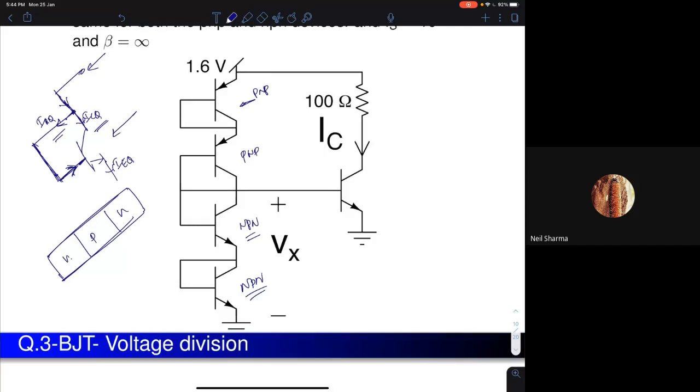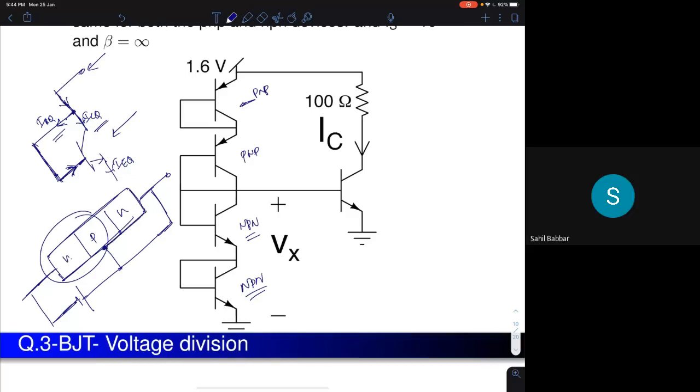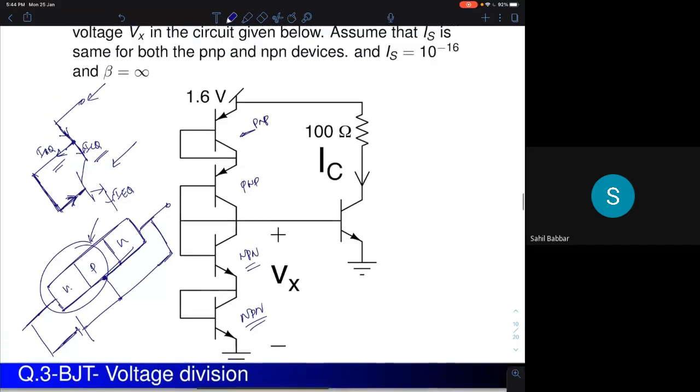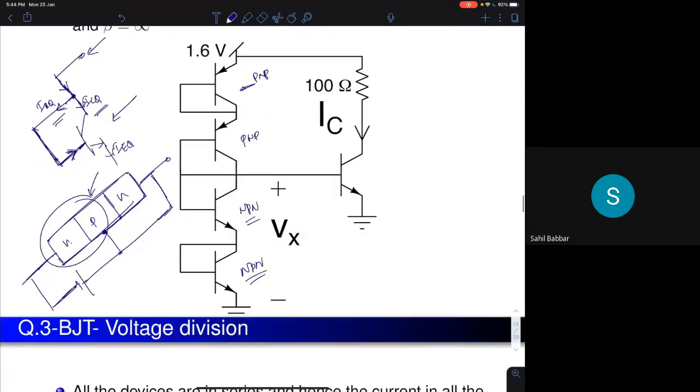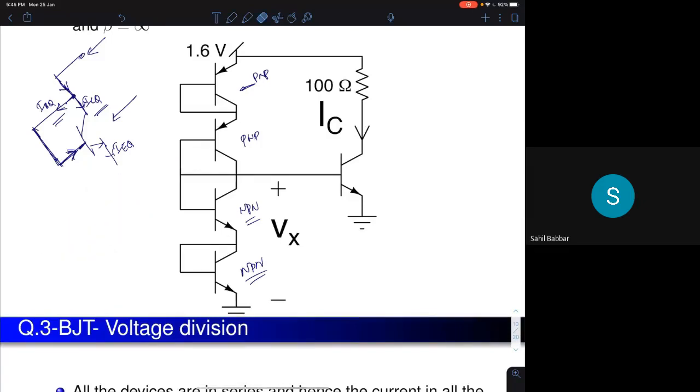Does that make sense? Or you can look at it from the device also. You have short circuited these two terminals. Once you short circuit these 2 terminals, what will happen? If you apply a forward bias voltage here, this is a forward bias voltage for the PN junction. This is your base emitter junction. If you apply this, it will flow like a conventional diode. Because your base width is very small, such a diode is called a narrow base diode. Is that clear? Maybe I can explain that after the class. I don't want to interrupt a big class for that. If you have doubts, I'll explain after the class.